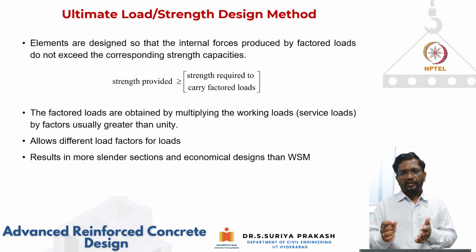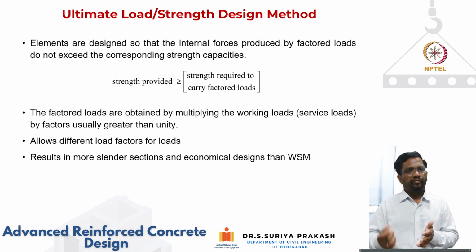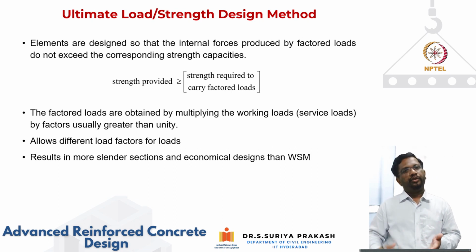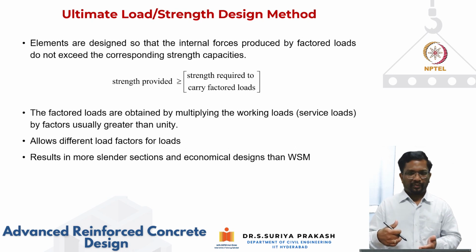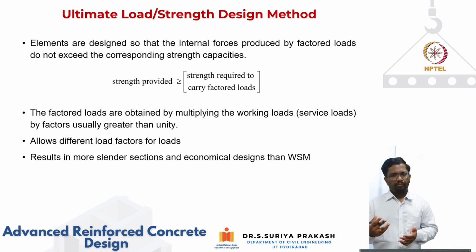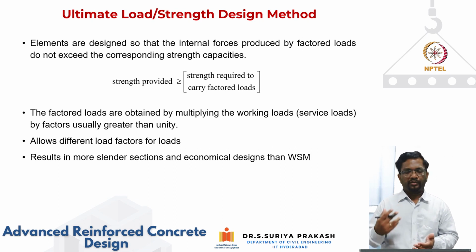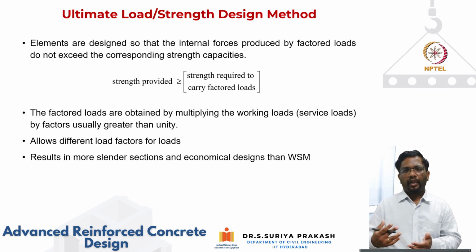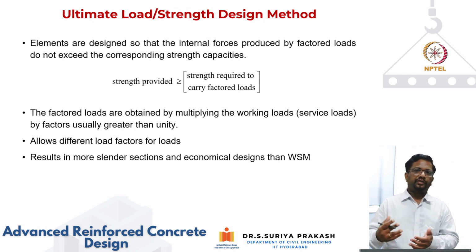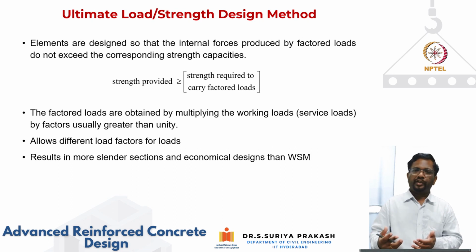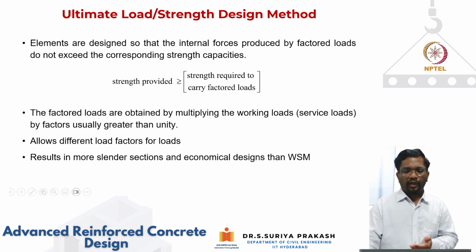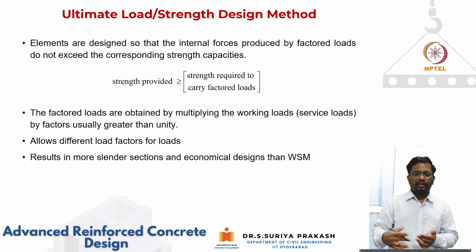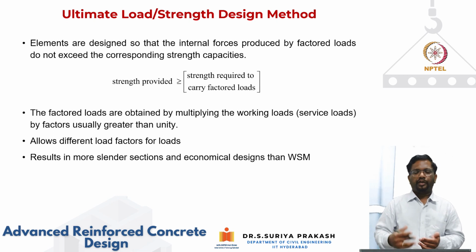So you are going to have less curvatures, and you're going to have less crack widths and less deflection. The moment you have less crack widths and less deflection, your durability performance is going to be much better. That is why the structures that were built even 100 years ago, some of the bridges we are still using, because they were heavily over designed, and under service loads, their stress levels in the steel and the crack widths are very limited. Okay, so that is the thing. But however, in ultimate load method, because we are using the maximum strength of the material, you end up with more slender sections and they are more economical.